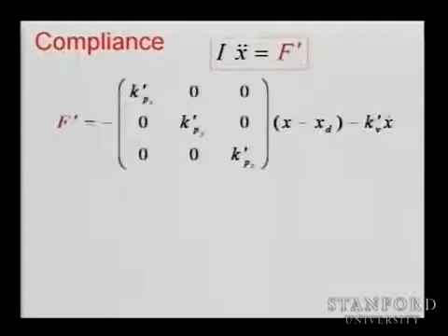So if we think about the controller f prime to be just a proportional controller, you're controlling x, y, and z, and you have a kp prime, kp y prime, and kp z prime, right? So what is the behavior? You push here, and you're going to feel some stiffness, right? And this stiffness is going to come from your mass times kp prime. It's the overall stiffness.